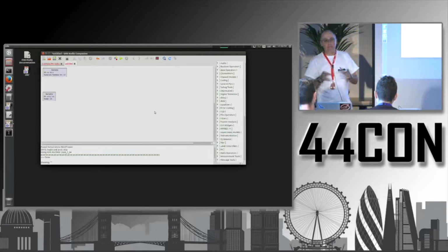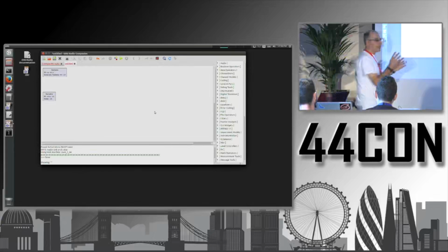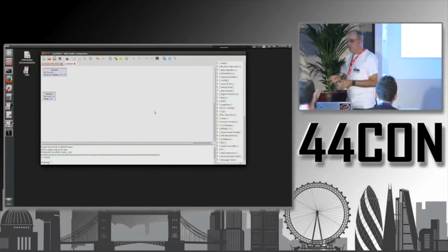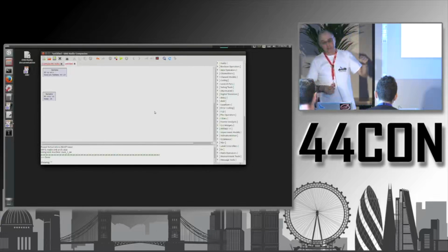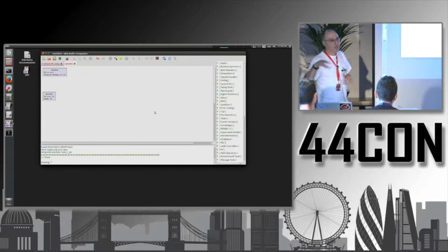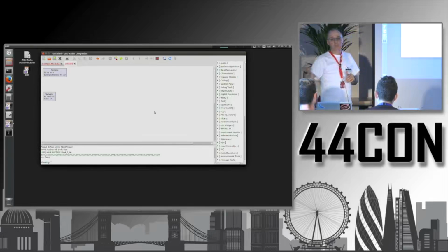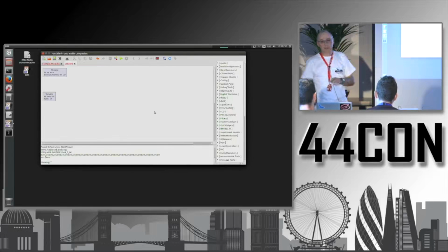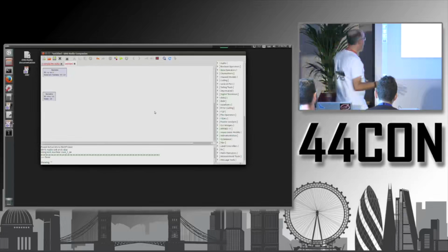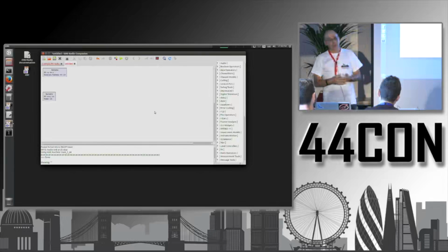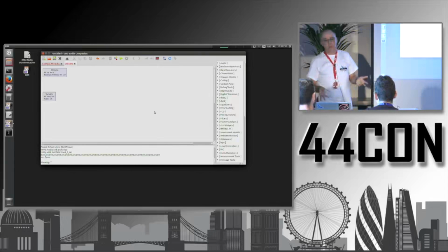That's an AD converter, analog to digital converter. An analog to digital converter takes a continuous signal and produces a discrete signal. And you have to define the speed at which it has to do that. For example, take a sample every second. Now that would be good for a very slow moving signal, but nothing like audio or radio.